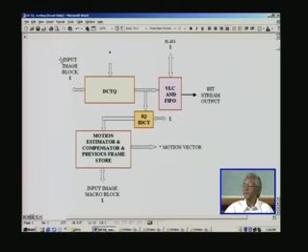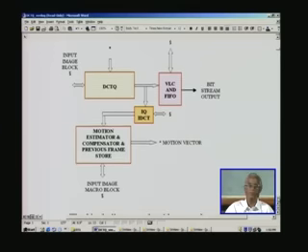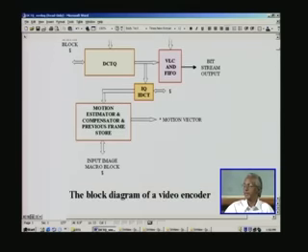Ideally we will be having a look at the images that we get out of running our design using both MATLAB as well as Verilog later on. So is this clear to you? This is the encoder, its counterpart is the decoder. So what goes out is a highly compressed stream. For example, whatever is the image, you compress by a factor of 10 to 50 anywhere, and then only send it here. Thereby you reduce the bandwidth requirements as well as storage at the receiving end.